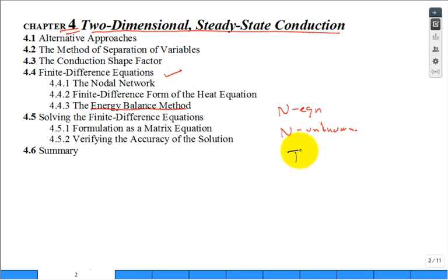It will be the temperature at location 1, the temperature at location 2, all the way to location n. You solve for temperatures at locations, and that's a mesh. That's a finite difference approach. And then once you have it, you can answer questions and do some calculations, like what is the rate of heat transfer through this material, what's the efficiency, other things. So how do you set up and solve n equations and n unknowns?